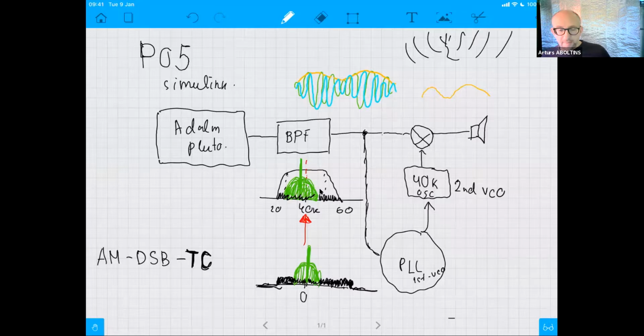It will happen immediately when some station is in the bandwidth of the filter and also in the band of PLL automatic tracking. You remember that last time you could have quite big offsets. It was in hertz, like if you had a 100 hertz center frequency, we could offset even 10 hertz.